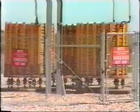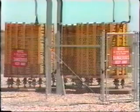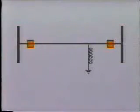We have mentioned in earlier tapes that when reactors are installed, they are usually connected directly to the transmission line. In this case, automatic reclosing should not be applied. This is because a fault in the reactor is more likely to be permanent than temporary, and we certainly do not wish to reclose and re-energize into the internal fault of the reactor. The same thing goes where a transformer may be directly connected to the line.